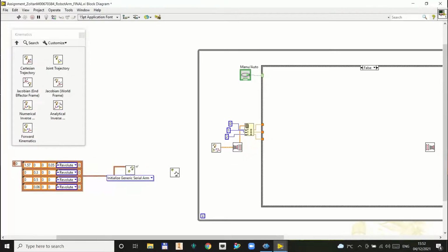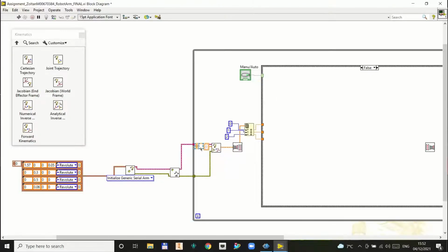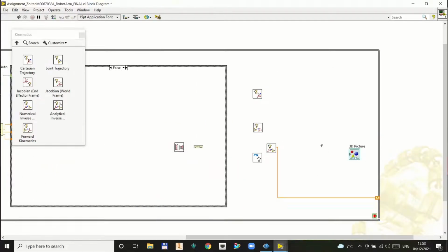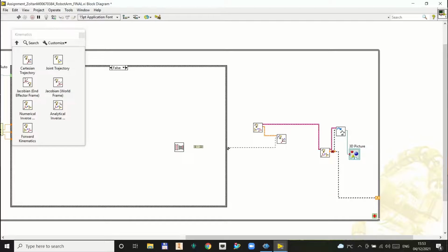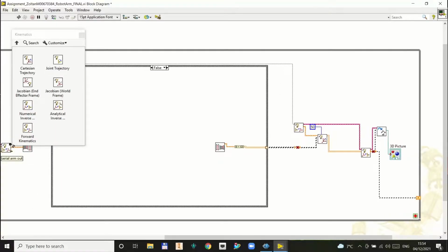For simplicity, the dynamic properties of the arm are not used in this example. Initial joint positions are given to successfully calculate the 4x4 transform matrix. After changing the coordinates of the end effector to the desired new coordinates, the inverse kinematics block is used to calculate the required joint positions to achieve the right tool position. Shift registers make it possible to use the changed positions as the initial positions in the next loop.